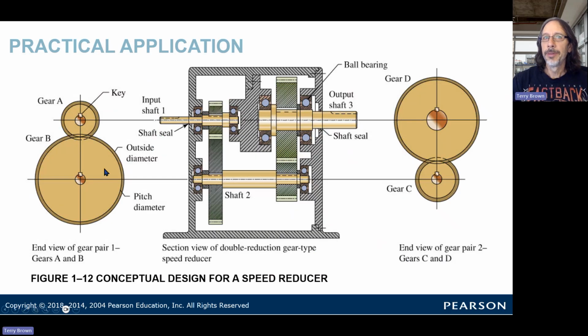Again, another diagram showing you just the gearbox or the speed reducer, torque increaser. So we've got two sets of gears here, compounded to give us a greater reduction. So input shaft, bearings, gears, first stage of gears here, and then another drive shaft, second stage of gears, sitting here in bearings. So in having done this subject, you should be able to do the calculations to enable you to choose bearings, size the shaft, size the gears for this kind of application.